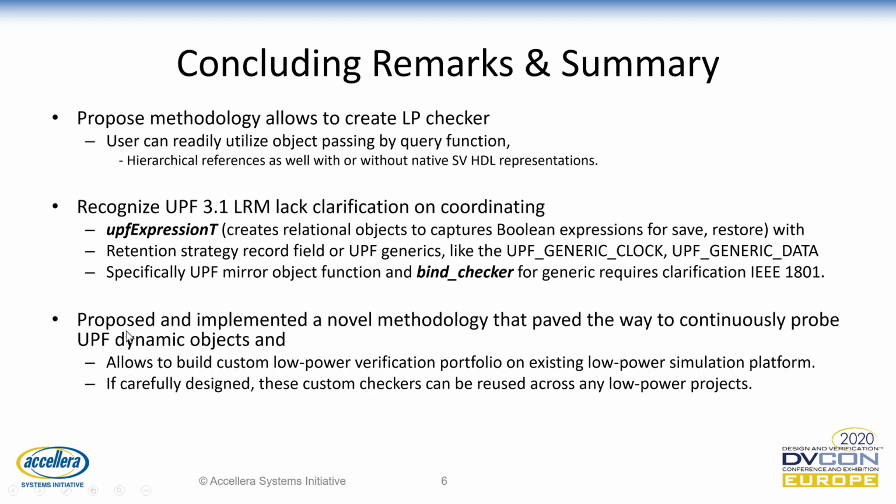We also conclude that we proposed and implemented a novel methodology that paved the way to continuously probe UPF dynamic objects and allows us to build a custom low power verification portfolio on an existing low power simulation platform. Just like we built a retention verification checker, we can also build isolation, power switch, or anything that you want to build. So if carefully designed, this custom checker can be reused across any low power objects.